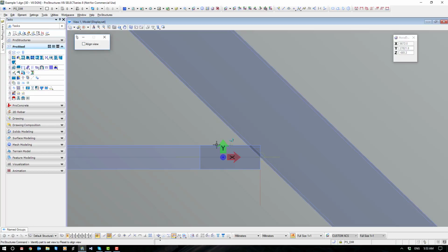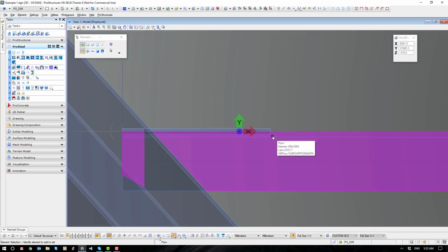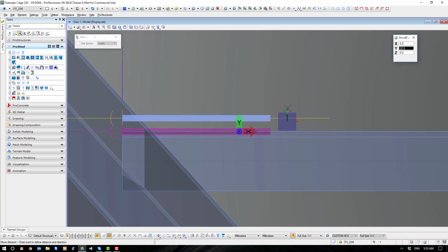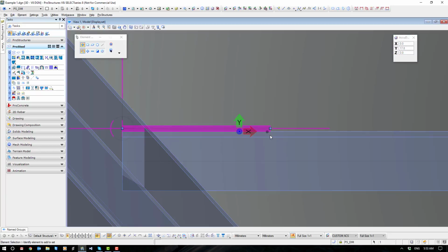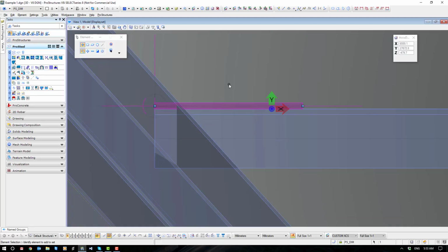Again, I don't really want to have a quirky view, so okay, and you can see there, put it smack on the center line. It's not always going to put it there, so just be a little bit careful, always check your view. So I'm going to move that 5 millimeters, placing that cleat on the outside face of my angle, like that.